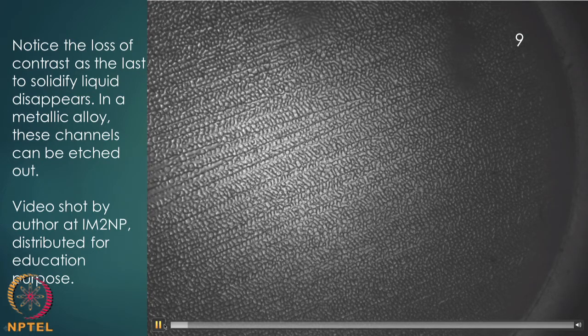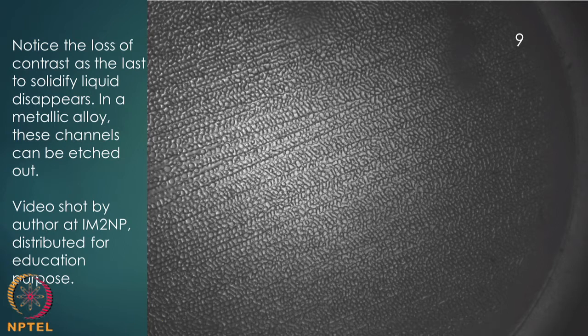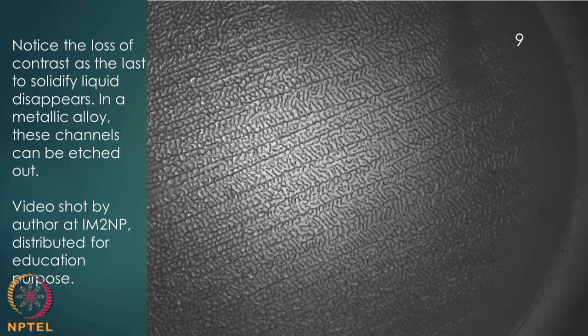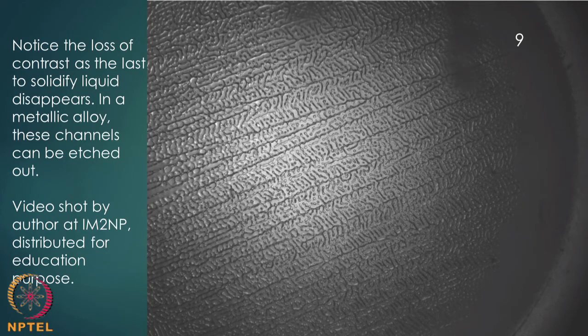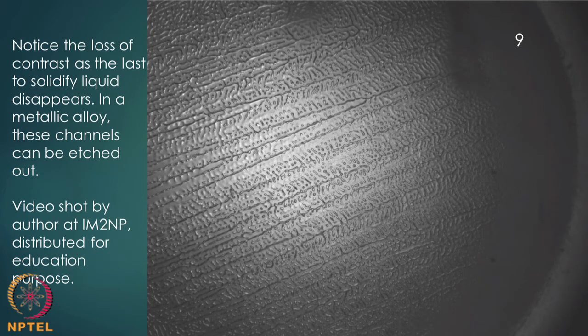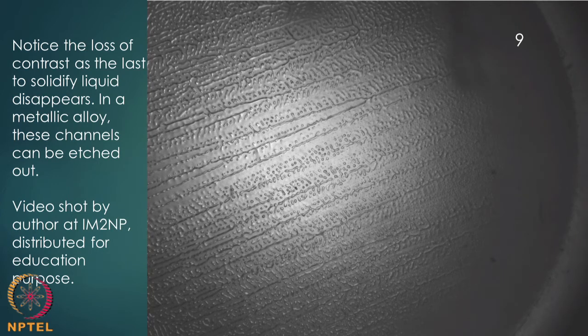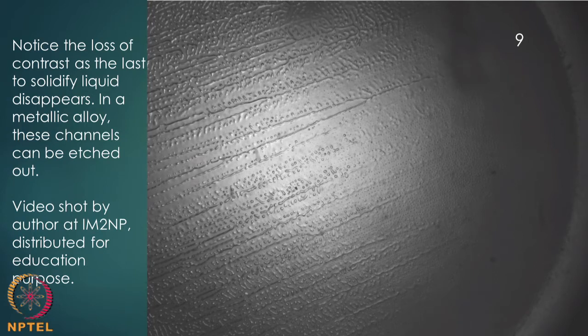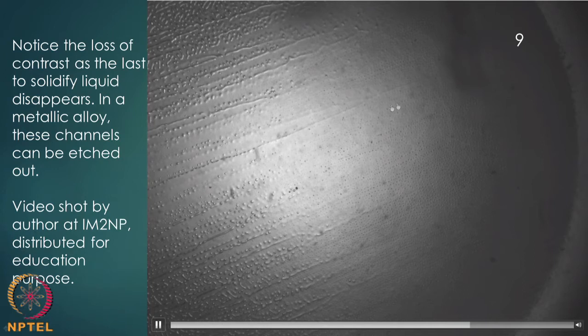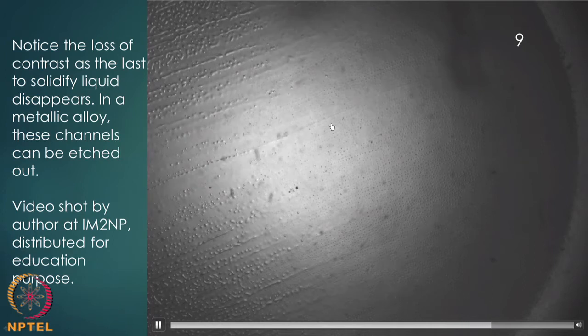So, here you can see the video, and as you keep watching, the features are becoming more and more clear, and then slowly you would see that there is a channel that is appearing as a line, a set of parallel lines, and then these patterns are going to become dots, and then finally those dots are also going to disappear. So, essentially the last to solidify liquid is being solidified in this particular run, and you see some boundaries that are remnant of the last to solidify liquid, which will be evident when you etch a metallic sample.